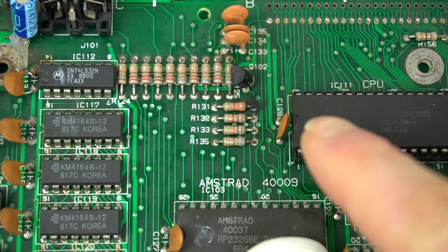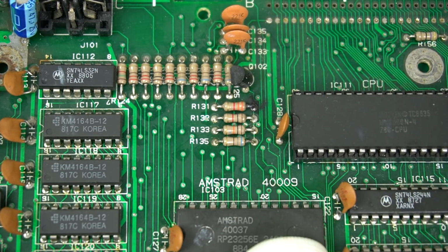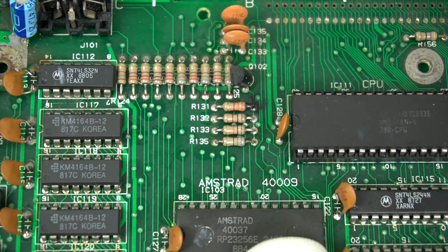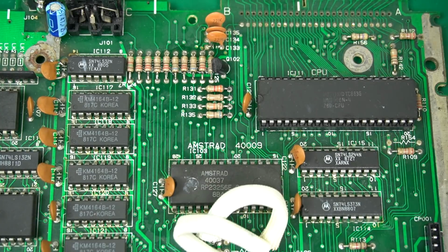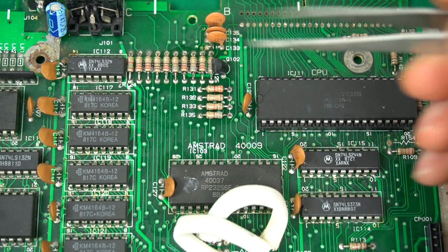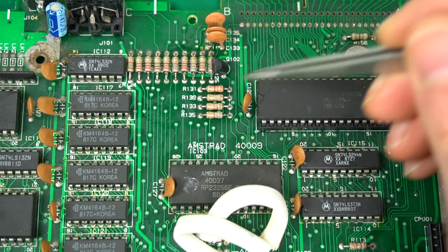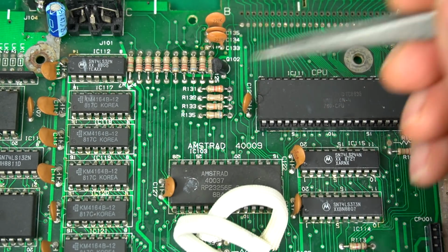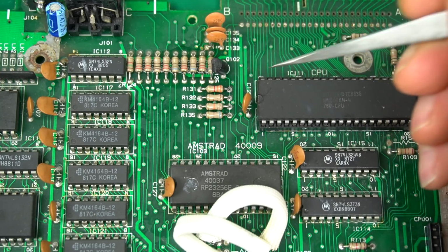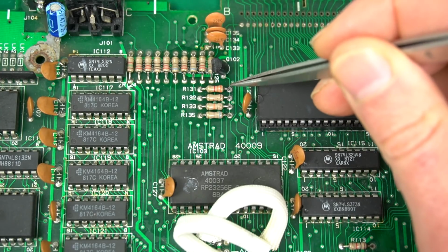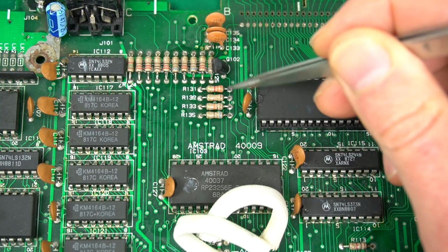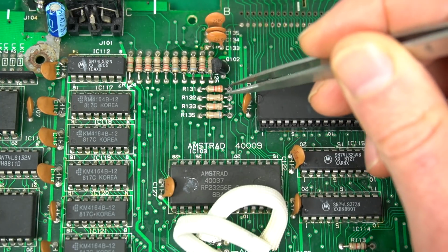So what about that charred area? It doesn't seem to be affecting anything, but we should at least make sure that everything is the way it's supposed to be over there. So just give it a really quick brushing with alcohol and the black stuff disappeared completely. So I wonder if that wasn't burned, but it was actually like a marker or something, and I thought it was burnt. I mean, it had all the telltale signs, but it seemed to just disappear right away with alcohol.